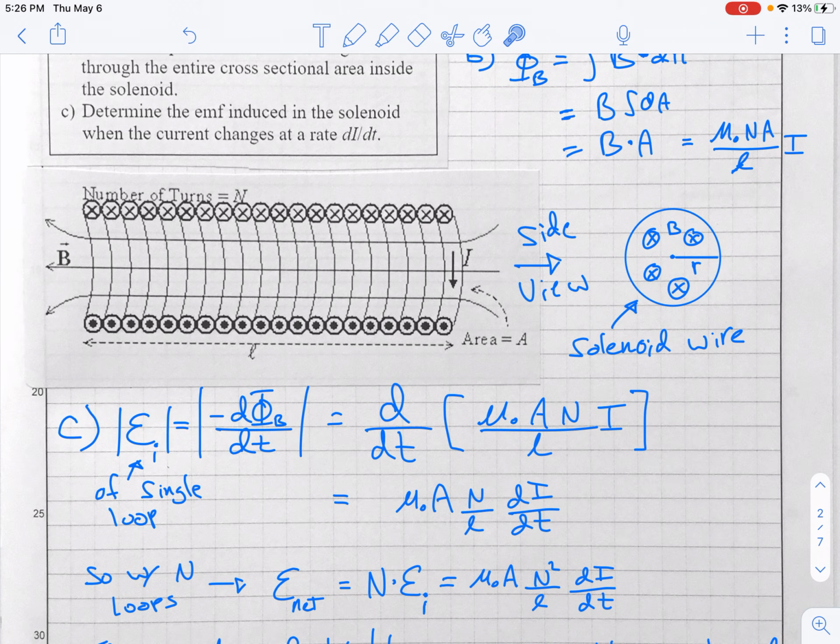If you think about a resistor and a solenoid connected to a battery, let's say you have a 10-volt battery, a resistor, and a solenoid. Well, there's 10 volts across the battery. That means the voltage across the resistor and the solenoid have to add up to 10. So if current is steady, you have 0 volts across the solenoid, and you'd have 10 volts across the resistor.